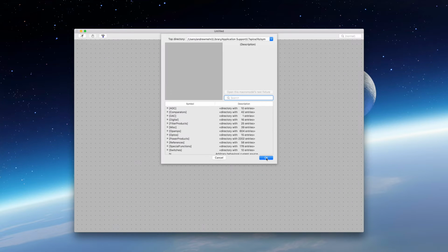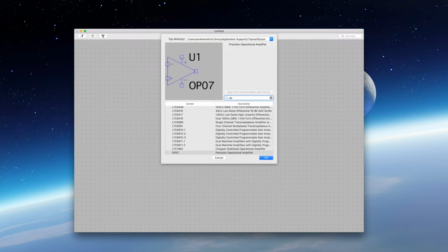We're going to use positive feedback to create the oscillation, and we're going to utilize the negative feedback to control the amplification factor. And in circuits like these, you want an amplification factor of 3. So let's go ahead and pull out a component, and let's start with an op-amp.